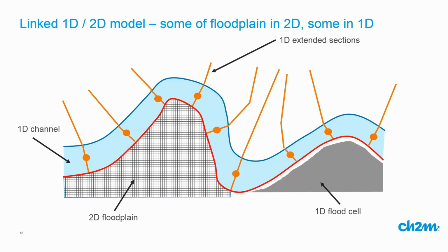Now why would we want to do this? Well, perhaps it's because the bottom right, where the 2D domain is, where it enables higher accuracy, perhaps that's where the houses are, where the town is, and we want to model the flows down the streets to come up with our flood map, or to assess the benefits of different flood risk management actions to see the change in number of properties affected. So we want higher accuracy in there.